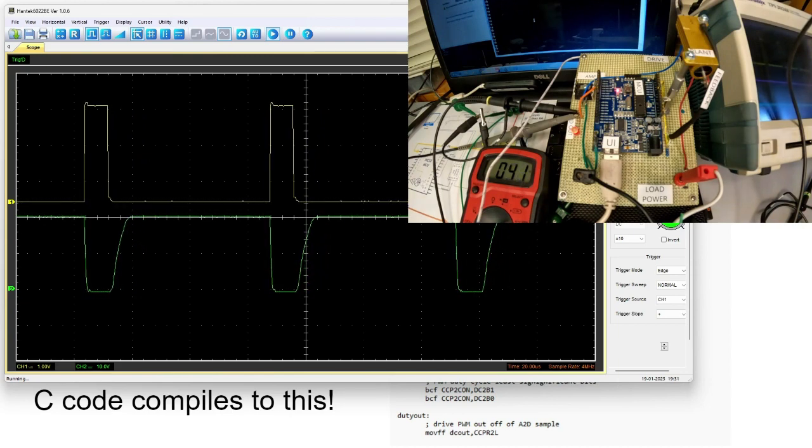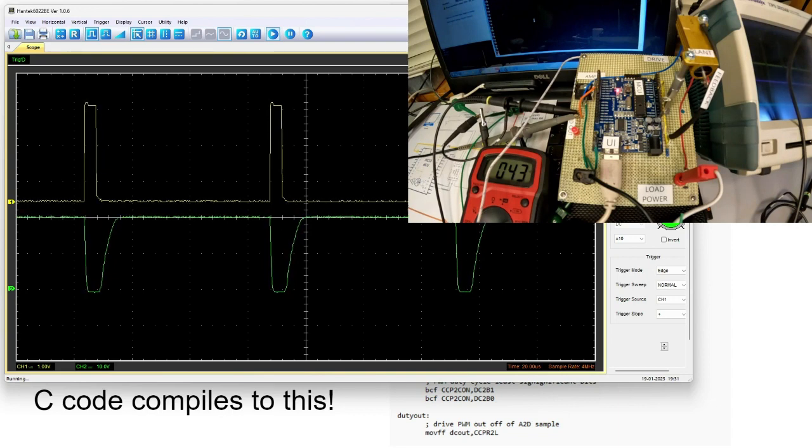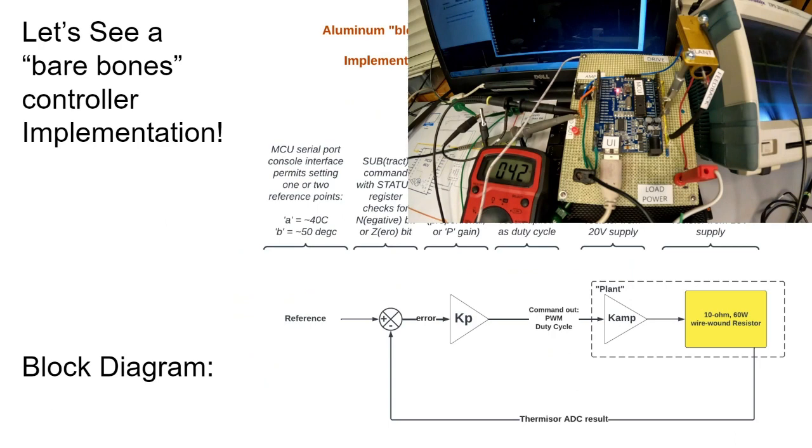So that is a complete electromechanical system. The mechanical phenomenon that we are controlling is the surface temperature, and we are using a power resistor as our heat source. And we've closed the loop in assembly at a very low level with a microcontroller. We've really got every element of a control system implemented here. If we were to look at our design to close, next steps would be to model this and understand its time constant. That's an important closing point, though. Very little modeling was done here. We will have a problem with steady state error in this setup. And that's where we'd introduce the notion of integral control, and we'll get to that later.